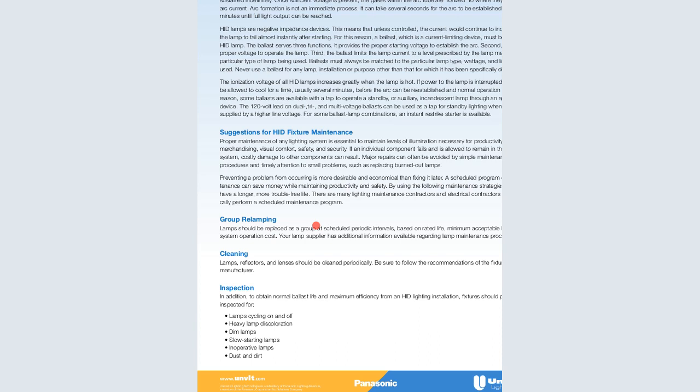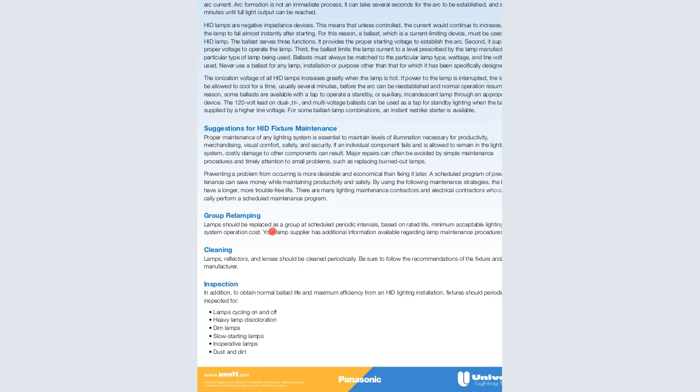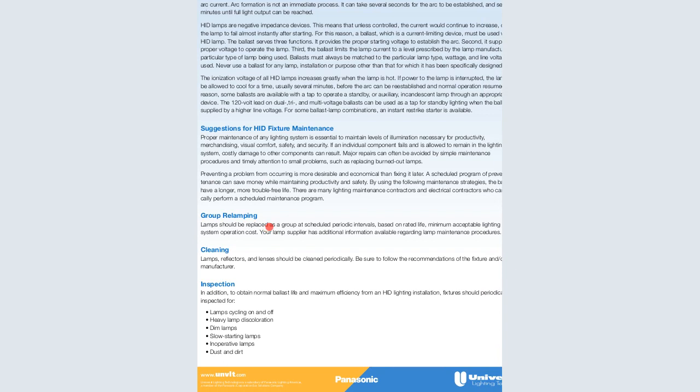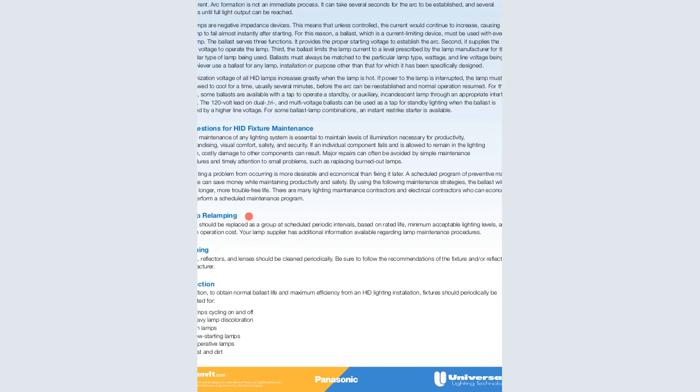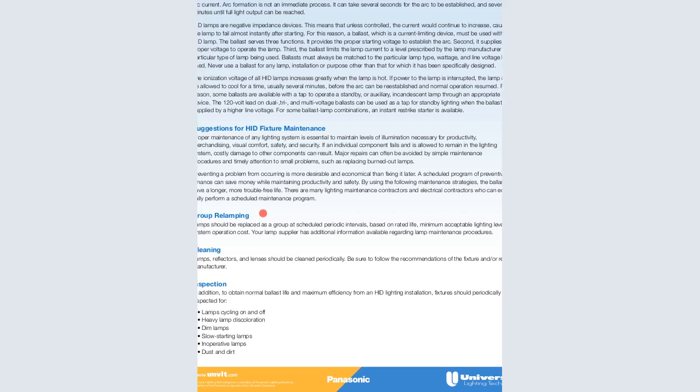For instance, with fluorescent tubes, if a choke is spoiled, or one part of the lamp is spoiled, we need to replace it immediately so that we can correct the problem. That is called maintenance. But if we leave that problem to persist for quite a long time, it will damage other parts and cause the destruction of the whole lamp.